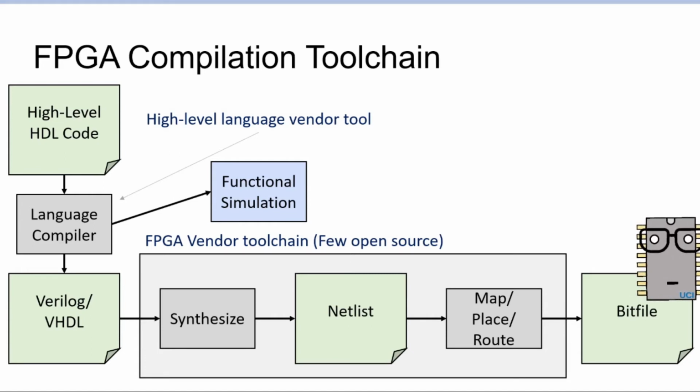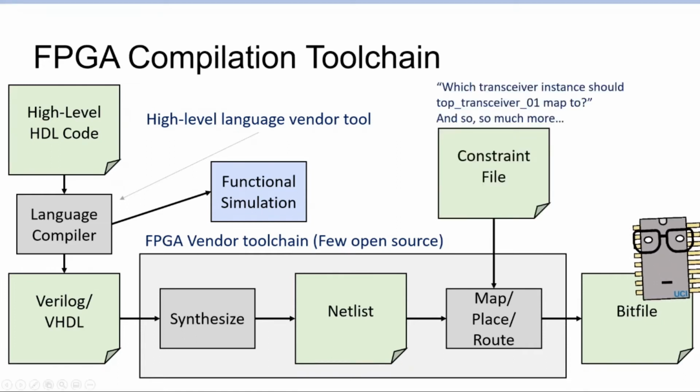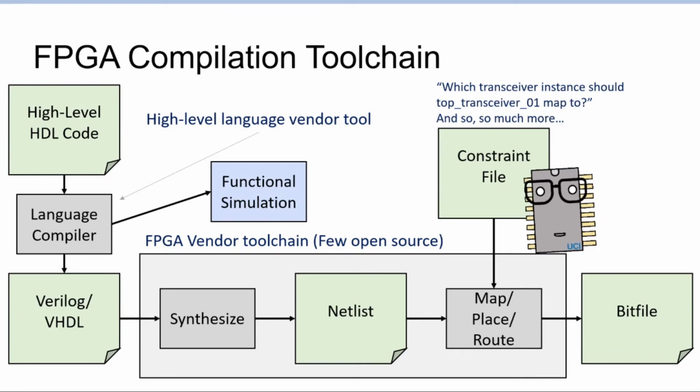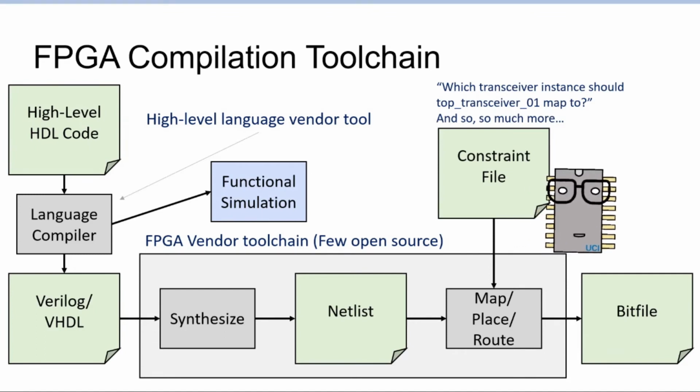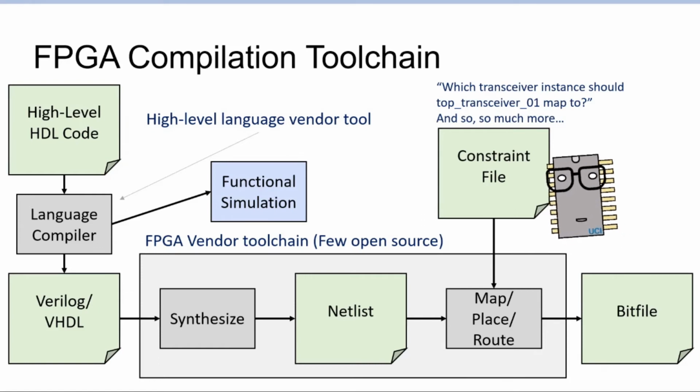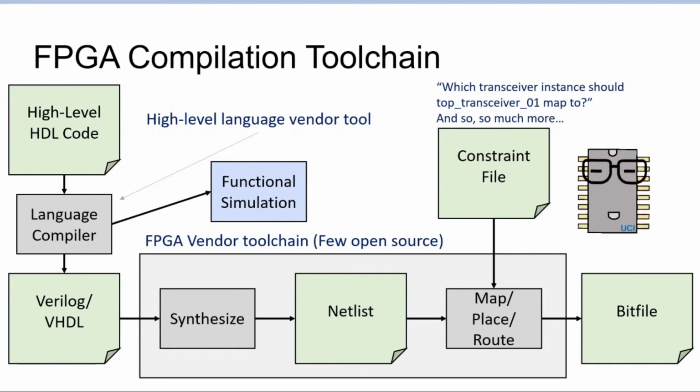Another aside is another thing that trips new FPGA programmers up a little bit, although for the purpose of Lab 2, I'll be removing this as much as possible: the existence of a constraints file. A constraints file is another thing that a programmer typically writes, which tells the place and route tool, for example, the clock speed that this whole thing is running at, by telling the compiler tool, oh, I connected a 100 megahertz clock to pin 2.